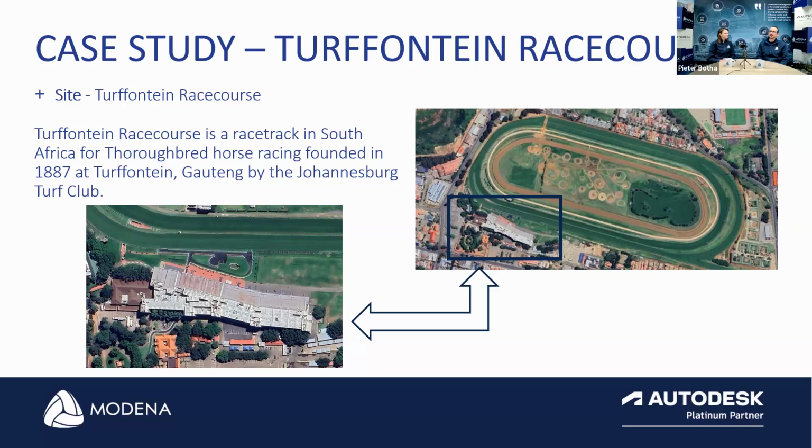Square meterage wise, it also depends on the environment that we are scanning. So let's use architectural as an example. We can do about 2,000 to 3,000 square meters in a day. It's also dependent on whether we're scanning for services and in-ceiling scanning.